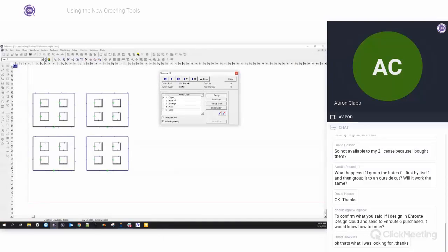That puts the primary focus on the order that you created when you selected them. If object is number 2 or number 3 in your list, EnRoute doesn't put nearly as much focus or priority on it, and so you might get some things not happening quite right. So that's why it's important to have object here at the top.